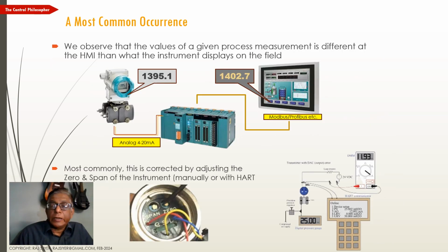Okay, today what I'll cover is the issue of recalibrating instruments so that their readings displayed in the field match the value that is displayed on SCADA for the same variable. Now, in such circumstances, it is common practice to open the instrument and adjust the zero and span settings or recalibrate the instrument with a HART transmitter.